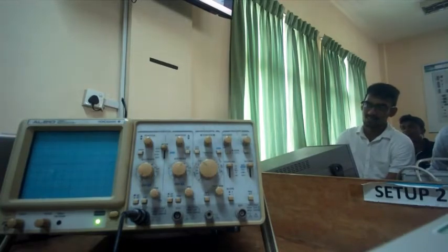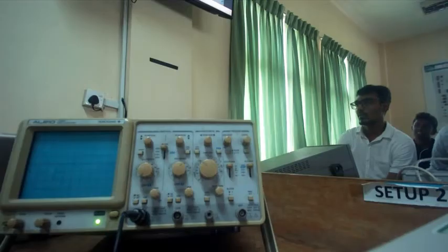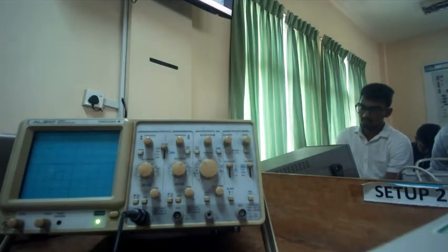This is V out, this is V in, this is V1, right? Let's assume this current is I. What is I? I is equal to V in divided by R1 plus R2. The same current flows through here, because I am not taking any current here. So therefore, output voltage V out is I times R1.